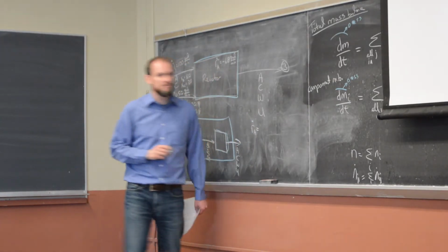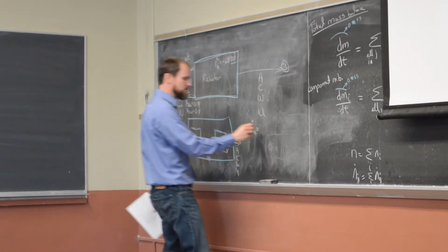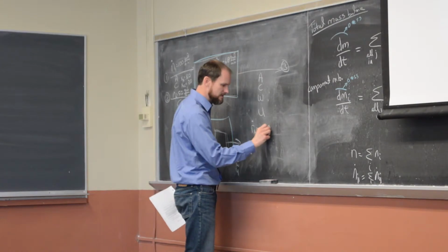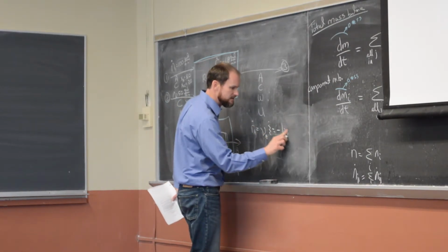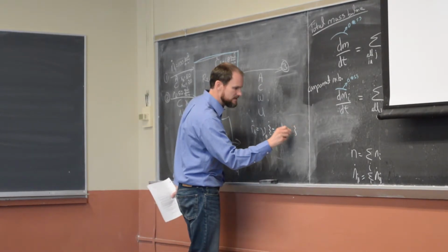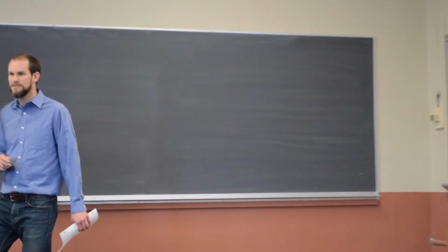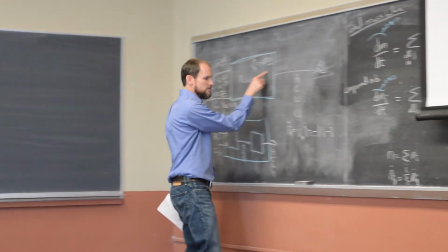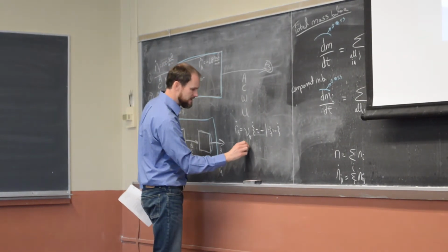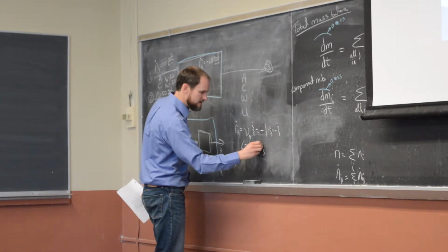If we define R A dot in terms of extent of reaction, ammonia is getting consumed, so nu A times xi dot is going to be minus 1 times xi dot, which is minus xi dot. So right here we know that 68 gram moles per minute is xi dot.